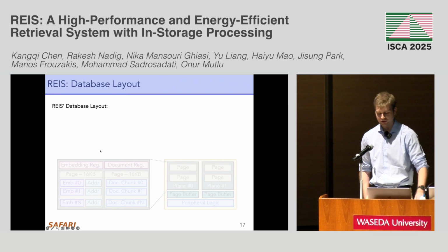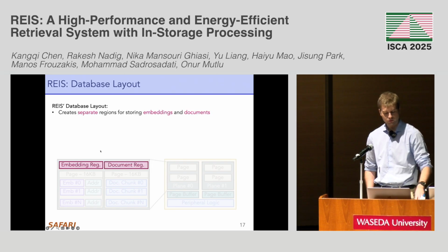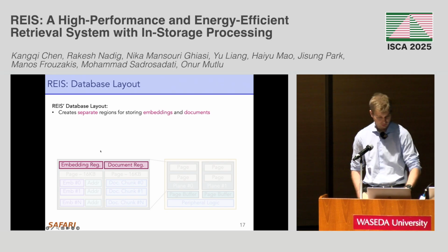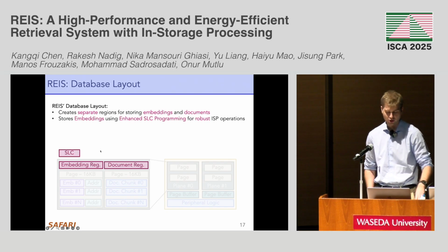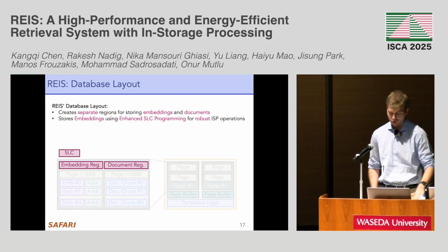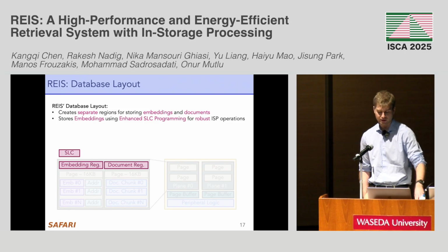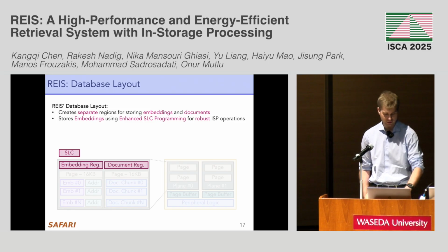Let's now move on to the database layout of our proposed design. REIS creates separate regions for storing embeddings and documents. It stores embeddings using enhanced SLC programming for robust ISP operations without error correction, eliminating thus any data movement overheads stemming from ECC.